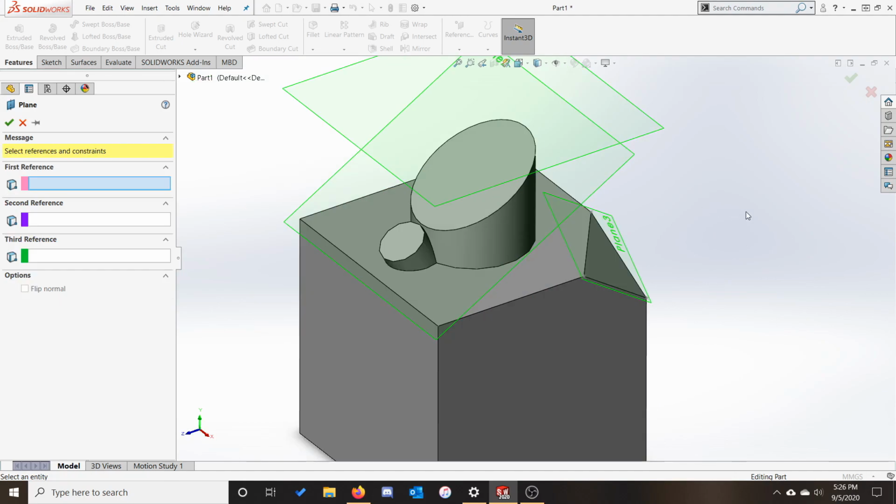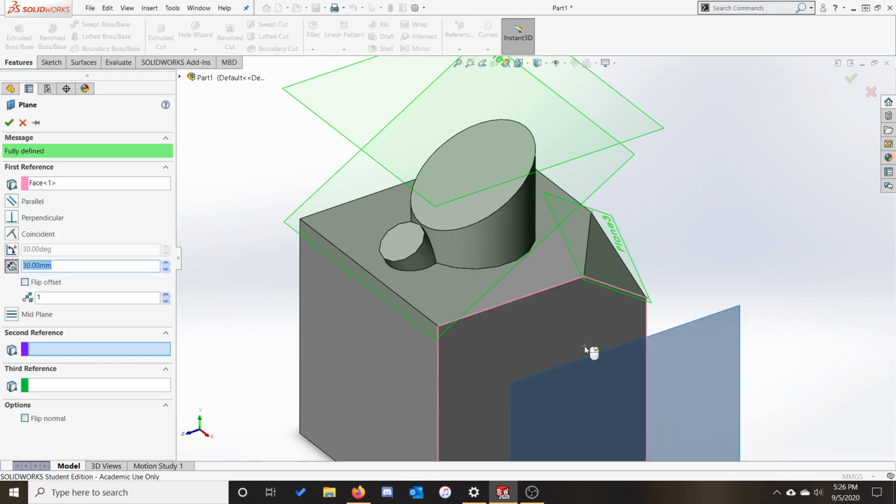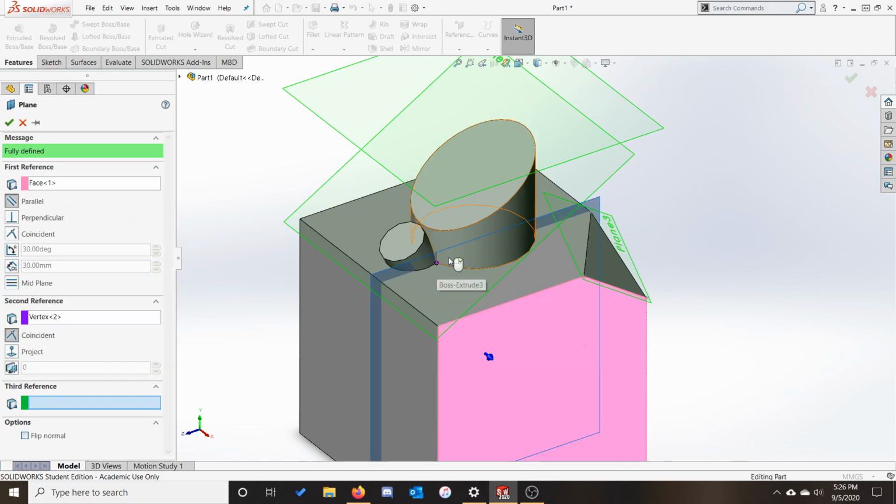The parallel plane also shows up fairly frequently. It works similar to the offset plane, in that first you need to select a surface, but this time instead of typing in an offset distance, we can select a point, and the parallel plane makes sure that the plane crosses through that point, while remaining parallel to the surface.